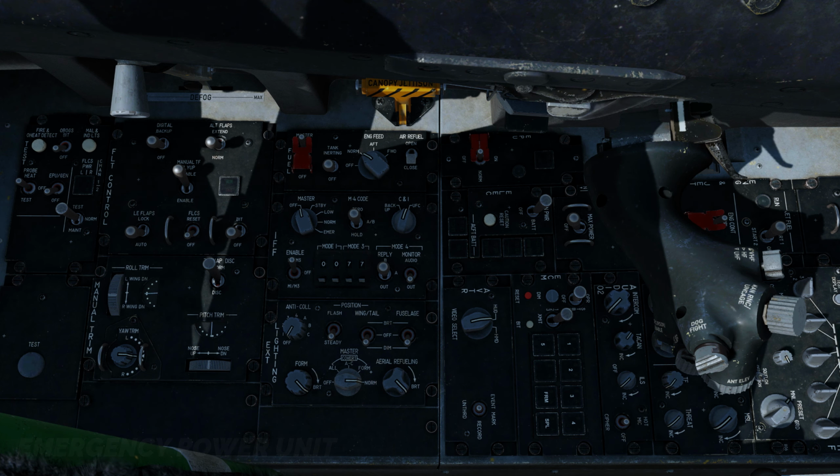The EPU provides emergency hydraulic pressure to System A and emergency electrical power to the emergency buses. It is automatically activated when both the main and standby generators fail or when hydraulic pressure falls below 1000 psi. To maintain operating speed, the EPU uses engine bleed air. If bleed air is not sufficient, hydrazine is used as a booster.